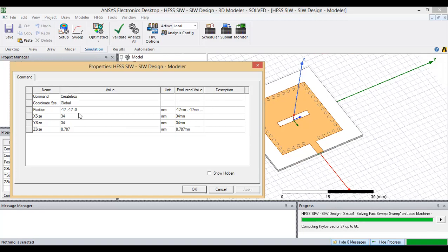Let's say we have designed this antenna and this antenna is not properly working. Let us change its slot, or let us change its length. So if we have taken a parameter, we can do those parametric analyses. Let's say I have taken the length of the patch like x equal to 2 mm. The antenna is not resonating. Then I can change the x value from 2 to 8.